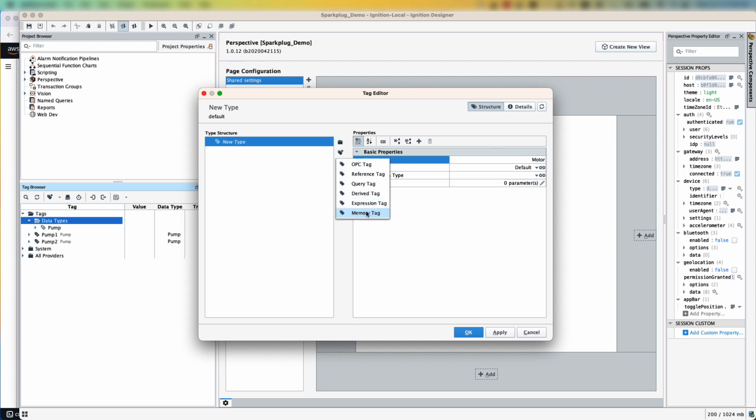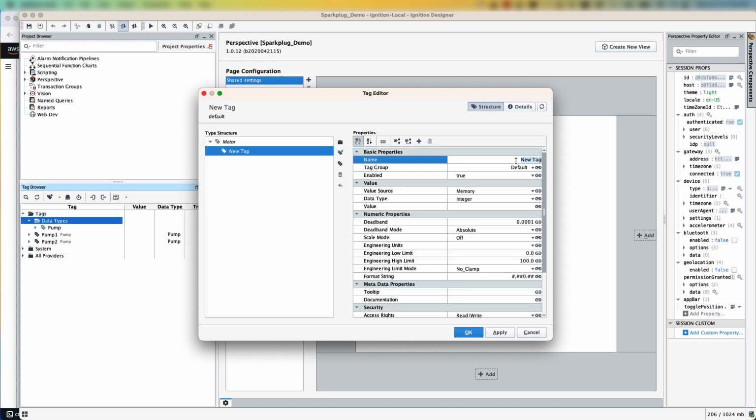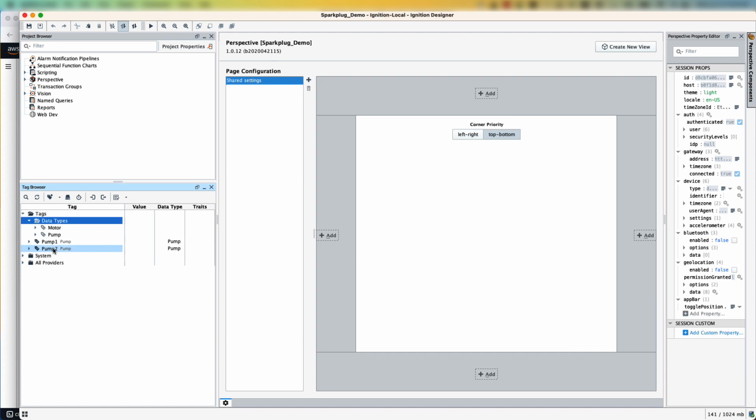And we'll add a measurement for RPM and assign some dummy value. So we have our new asset and model ready. So we'll force update and see how that shows up in IoT SiteWise.